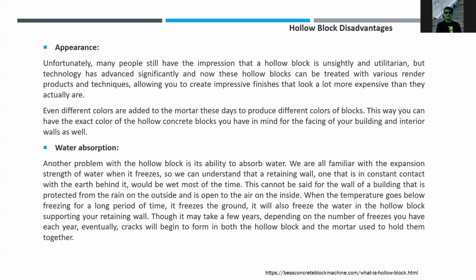One of the disadvantages is water absorption. Because of the hollow blocks, it has the ability to absorb water because it's porous. And in case you don't put fillings in the cores of the hollow blocks, those cores will accumulate water. Or sometimes it will accumulate pests like cockroaches and ants. The pests will be living in the cores of the hollow blocks. So those are the disadvantages.